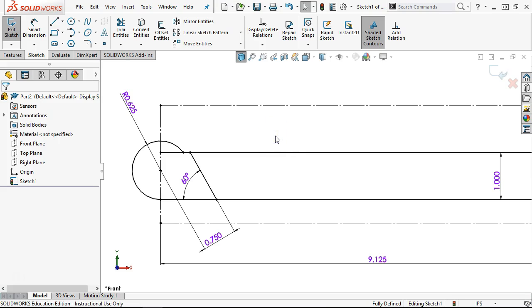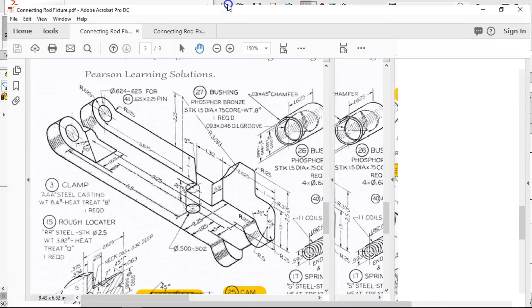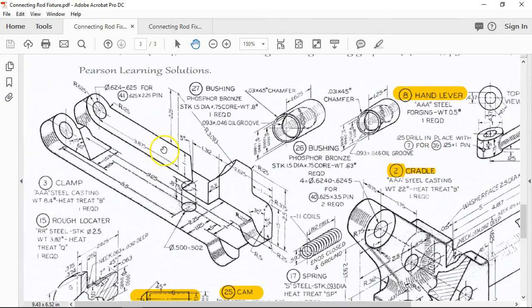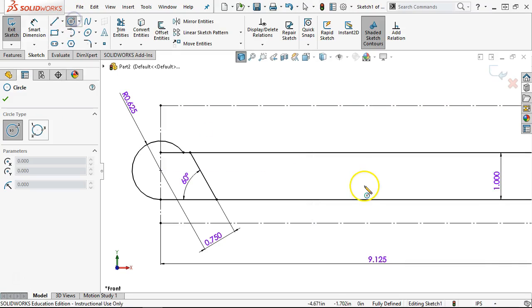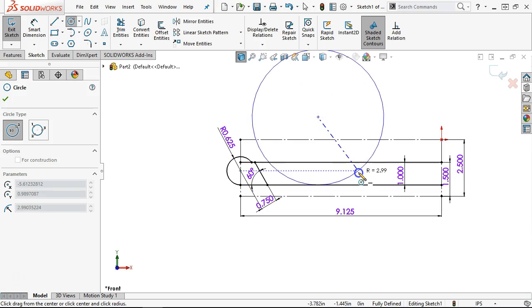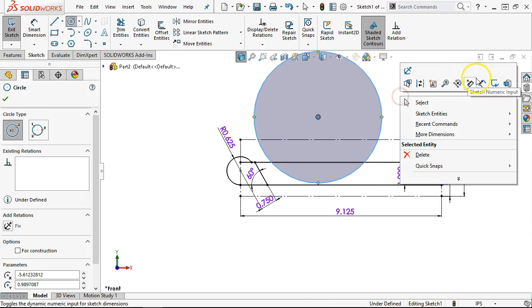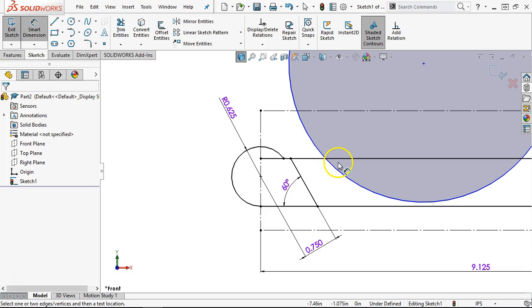Let's see, we have a radius. I'm going to fly this back in. All right, so trying to decipher 225 up and then a radius of 3.093. So that can just be a circle, and we'll pick up the arc wherever it falls out.